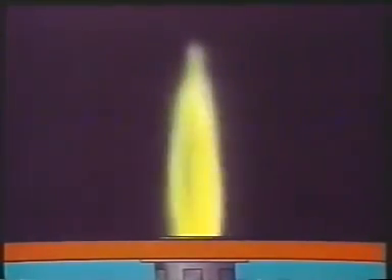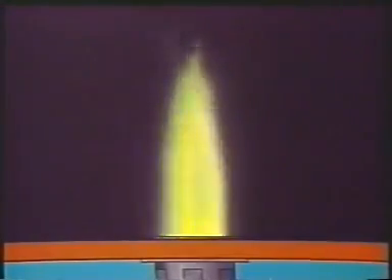A long, smoky flame is caused by insufficient combustion air or insufficient atomizing steam. The flame may be shortened by increasing primary or secondary air or by increasing atomizing steam. A thin, fluttery oil flame indicates too much atomizing steam is being used. A reddish, dusty flame with smoke over the bright part of the flame indicates a lack of oxygen for complete combustion.